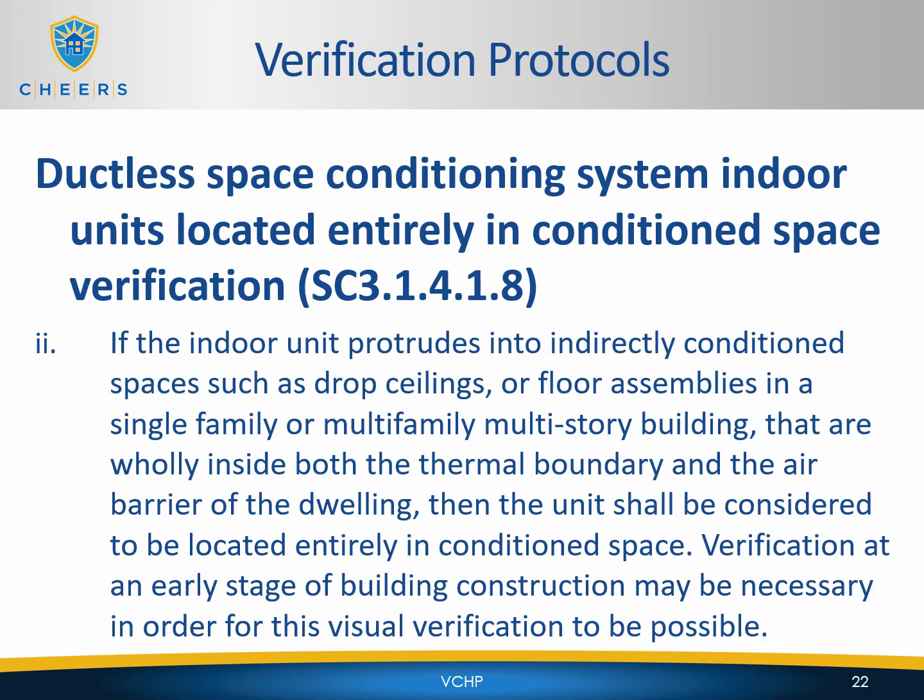If the indoor unit protrudes into indirectly conditioned spaces, such as drop ceilings or floor assemblies in a single-family or multifamily, multi-story building that are wholly inside both the thermal boundary and the air barrier of the dwelling, then the unit shall be considered to be located entirely in conditioned space. Verification at an early stage of building construction may be necessary in order for this visual verification to be possible.